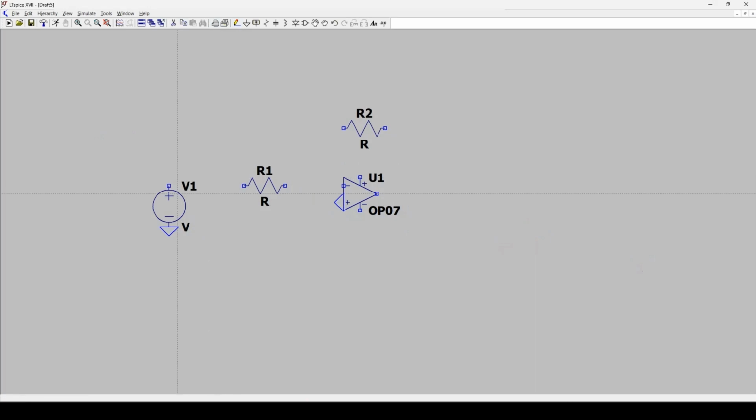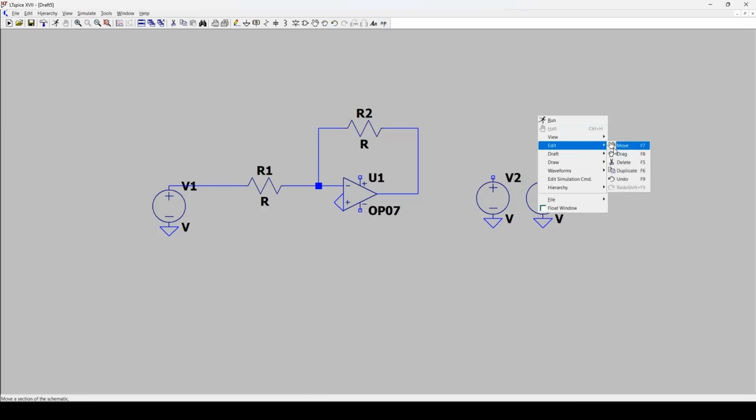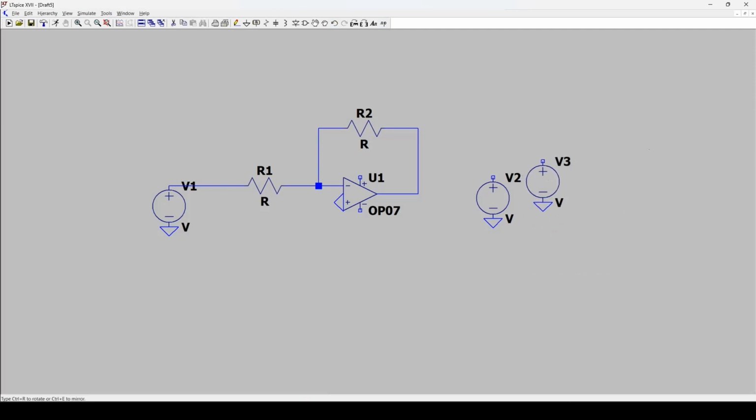And then we're gonna do some connecting. One thing to keep in mind while you're working with operational amplifiers is that they also actually need power sources. And this time I'm going to be adding 2 power sources, a positive and a negative power. And I'm actually going to rotate the negative power source, so it's a bit easier to draw a schematic for. I can also move the text. And I'm going to do some basic connections. So overall, nothing new, nothing we haven't seen before.